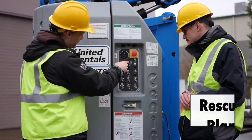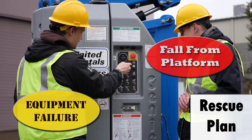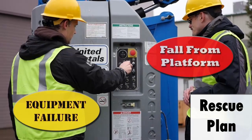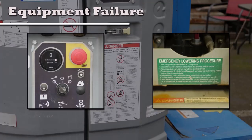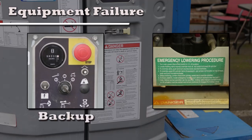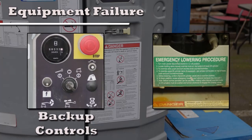Employers must have a rescue plan that covers equipment failure and a fall from the platform. This plan must return a fallen or stranded worker to the ground safely and quickly. For equipment failure, there are two major options. The operator can switch to the backup control system and lower the platform to the ground.